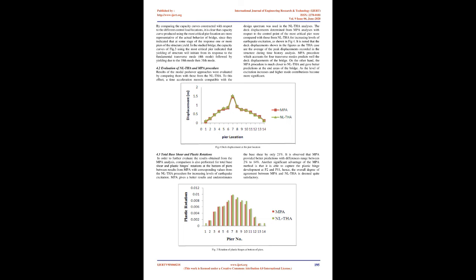In the studied bridge, the capacity curves of Fig. 3 using the most critical pier indicated that yielding of the structure will initiate from its response to the fundamental transverse mode, the fourth mode, followed by yielding due to the 18th mode, then the 31st mode. 4.2 Evaluation of NLDHA and MPA procedure. Results of the modal pushover approaches were evaluated by comparing them with those from the NLDHA. To this effect, a time acceleration record compatible with the design spectrum was used in the NLDHA analyses.